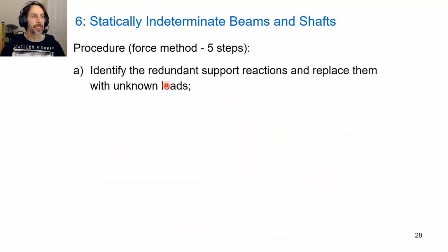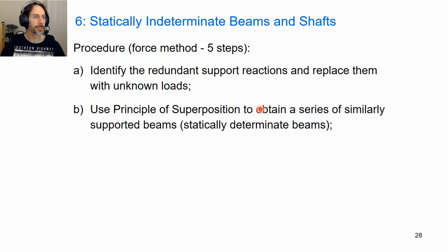Okay, so our procedure is to identify the redundant support reactions and then replace those with unknown loads. Where we have a redundant support, we don't know what the reaction is, so just put an unknown force there and we'll calculate that as part of the process.